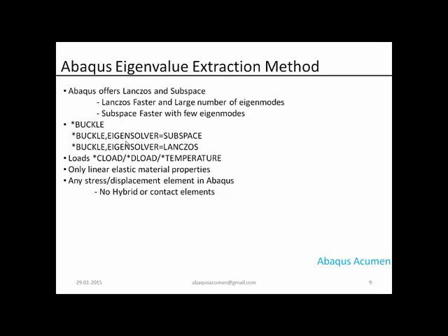So like a typical thermomechanical analysis, you apply a temperature, you apply a coefficient of thermal expansion, and you give the end temperature at the end of the step, and then Abaqus will calculate for this particular problem at what temperature the structure will buckle. So these are the three different loading choices you have.